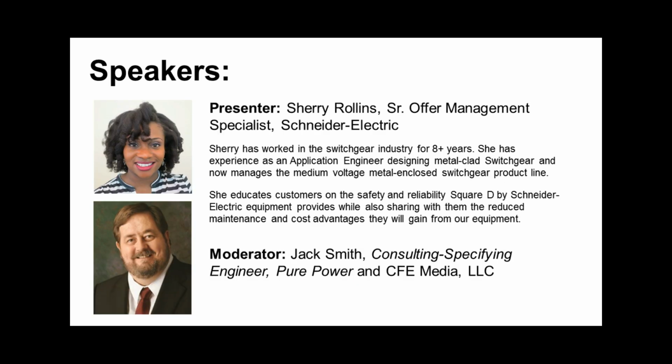So the first question: how do the grounding options for fixed switchgear compare to traditional grounding means for withdrawable switchgear? Well, excellent question. Hello, everyone. This is James Stacy. Typically, withdrawable switchgear is also coincidentally typically air-insulated switchgear, which could be either metal-clad or metal-enclosed switchgear per the ANSI standards.